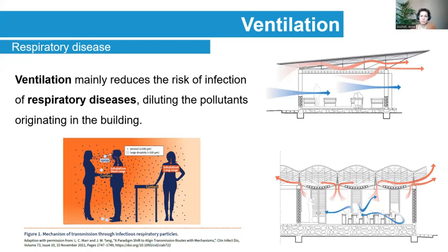Well, ventilation moves fresh air, normally outdoor air, into a building or a room and distributes the air within the building or the room while the stale air is removed. The general purpose of ventilation in buildings is to provide healthy air for breathing by both diluting the pollutants originating in the building and removing the pollutants from it. In case of respiratory disease where airborne transmission may occur, ventilation is a key strategy to reduce the risk of infection in the indoor environment, since we should consider the pathogen as the pollutant of our indoor air.